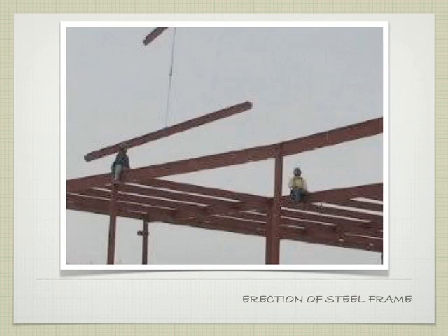So you've got that delay in the process. If they can build a 6-story building in 3-4 days, you don't want to wait for that concrete to cure for 28 days before you can move on and keep building. So typically it's going to be faster. There are other types of decking, like cellular decking, that doesn't involve the concrete topping. If you were using something like that, it would probably be more efficient to use the actual decking. Does that make sense? So if the decking takes too long, that's when you're going to use temporary decking instead.